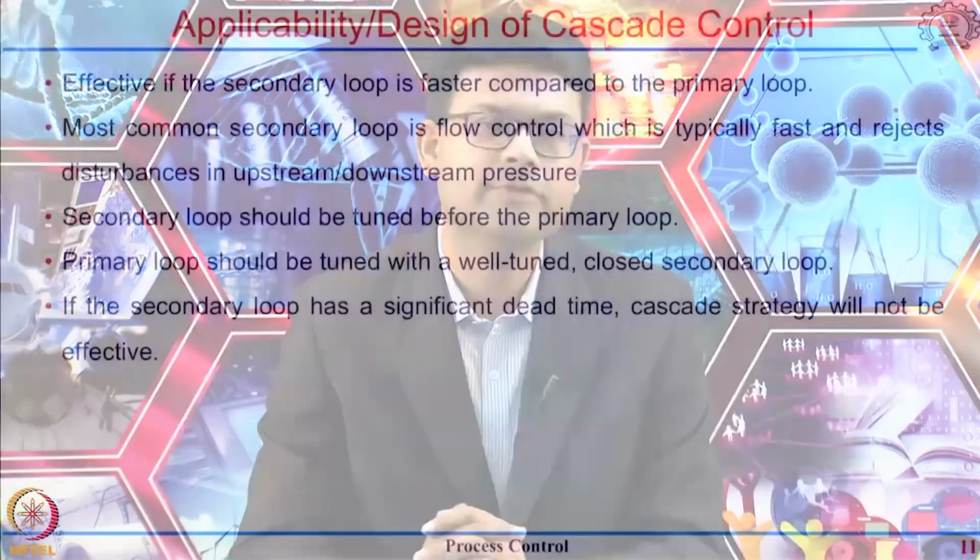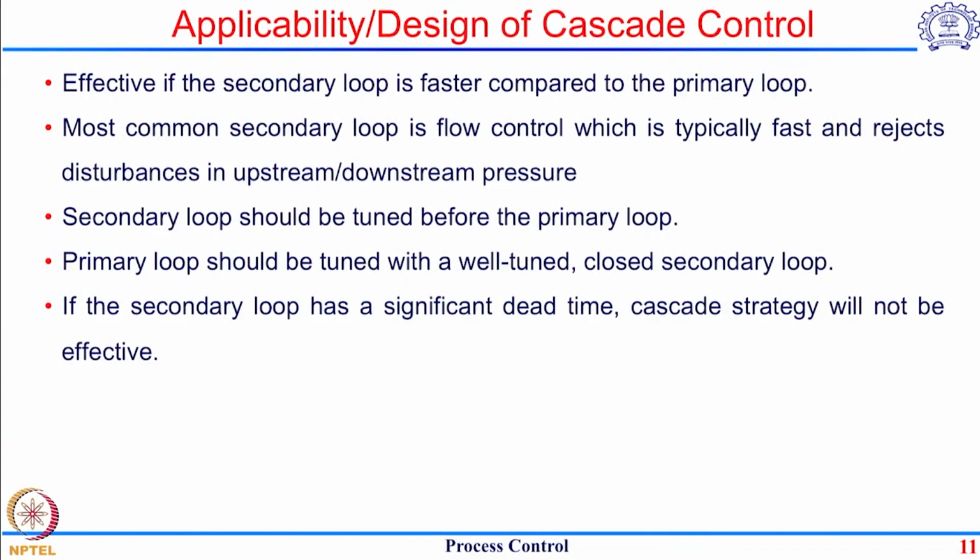And one last point which I would like to make is that this secondary control loop which we are using is merely to take some action, or to move the valve in the correct direction, in anticipation of or based on the disturbance. So, it is just a way to improve the performance. You do not necessarily need an offset free response here. As long as the valve takes an action before the disturbance affects the process, the objective of improving the speed of response of the cascade control strategy is satisfied. So, even an offset in the secondary control loop is acceptable.